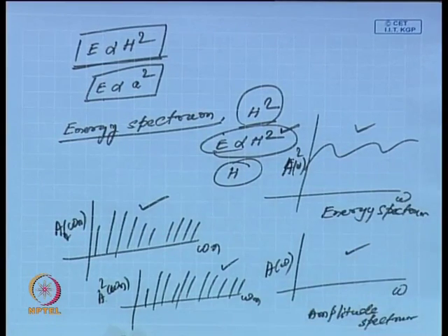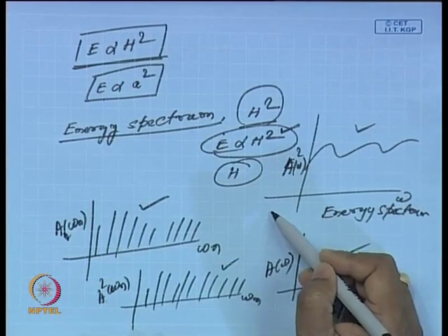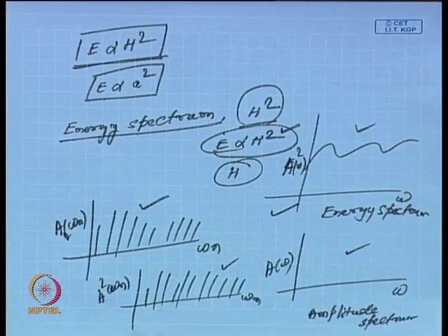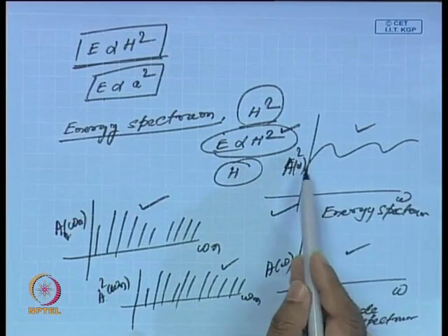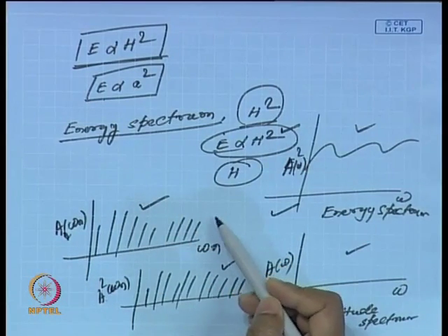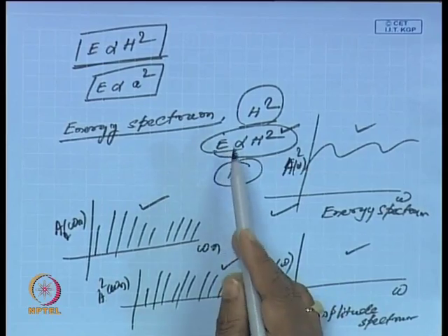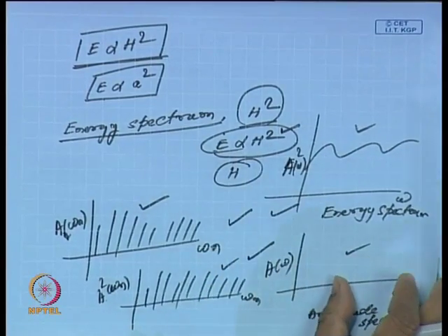So, this is very important in case of ocean data collection. Of course, I am not going into the statistical or probabilistic distribution of data here, but one has to make a note that when the amplitude spectrum is collected, the wave amplitudes are known, but in case of energy spectrum, the data distribution is in terms of energy spectra, then we say the amplitude square is known.